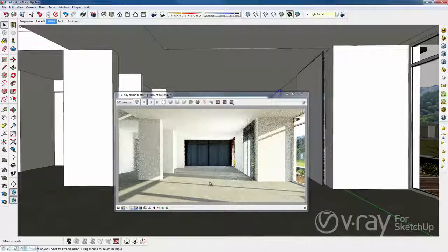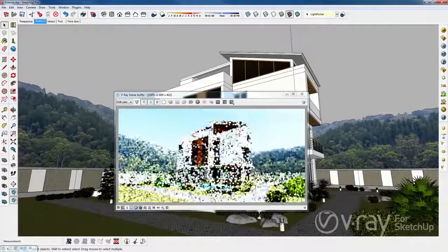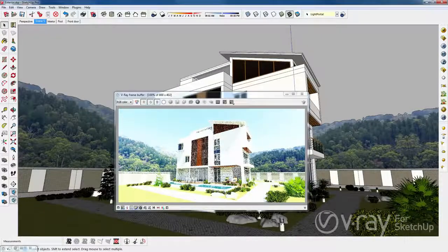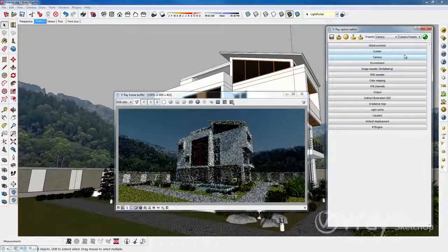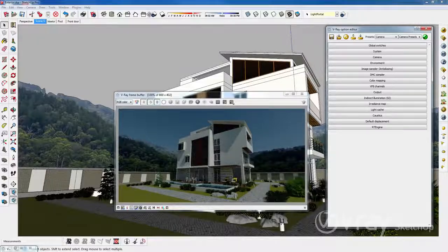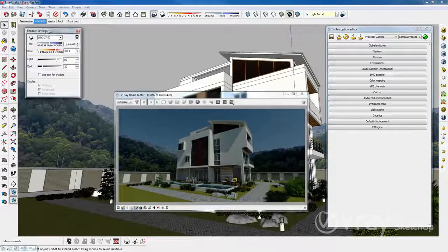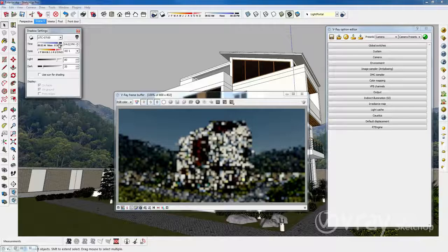Now that our client really knows how V-Ray RT works, he wants to see a simple night shot. First, I'll go back to the scene we saved for the daylight exterior shot. Then I'll need to change the camera exposure. I'll choose the After Sunset preset. Again, notice how the exposure changes automatically. Now I want to change the time of day to an evening time and adjust our sun angle.